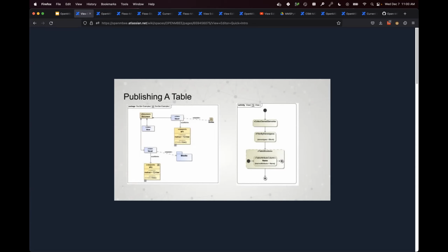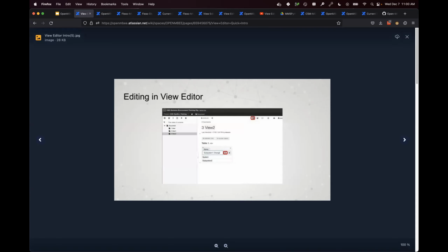Then you would create a table structure and specify what it is that you want your table attributes columns to be. In this case, we just want to take a look at the name, and you filter out the name property. So once you create this viewpoint, you create this DocGen diagram, you create this view diagram, you publish it to Teamwork Cloud, which coordinates a sync with MMS.